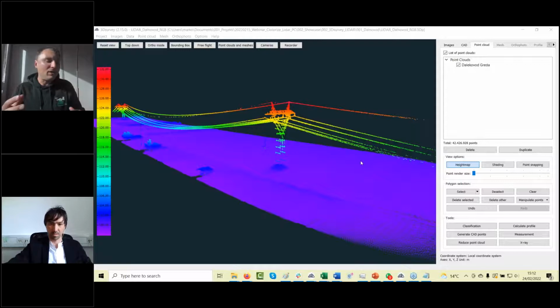But when we added a point cloud from the solid state LiDAR, we saw that the diameter of the power pole becomes bigger because of the noise of the point cloud. It looks like a weir of something under the power pole, and this is why the main issue is the level of noise and the reality of the point cloud.